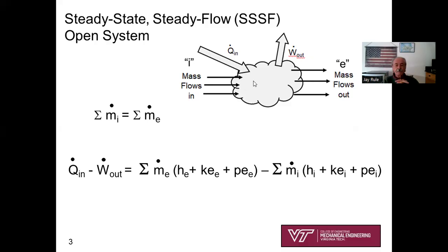We're eager to simplify. So we've got exactly the same sketch, but the continuity equation becomes really easy to understand, common sense. The sum of the mass flows coming in, if you add them all up, they've got to exactly equal the sum of all the mass flows out when you add them all up. It's a little bit like an accounting problem. That statement of steady state, steady flow, continuity.